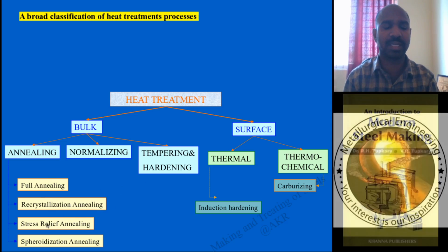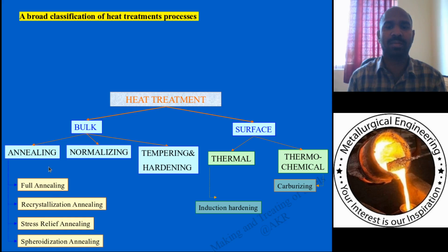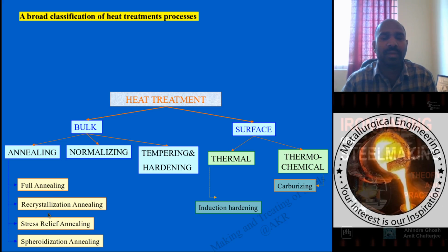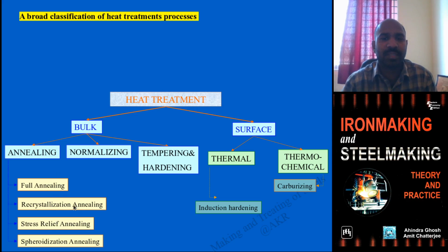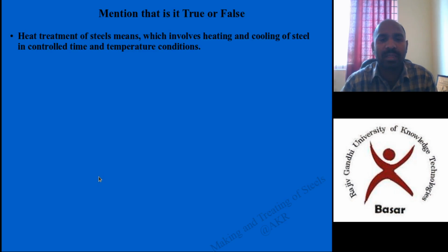Stress relieving relieves stresses retained from mechanical working. Recrystallization annealing nucleates and recrystallizes grains, improving strength. And spheroidization, of inclusions and grains, increases the strength of the material.